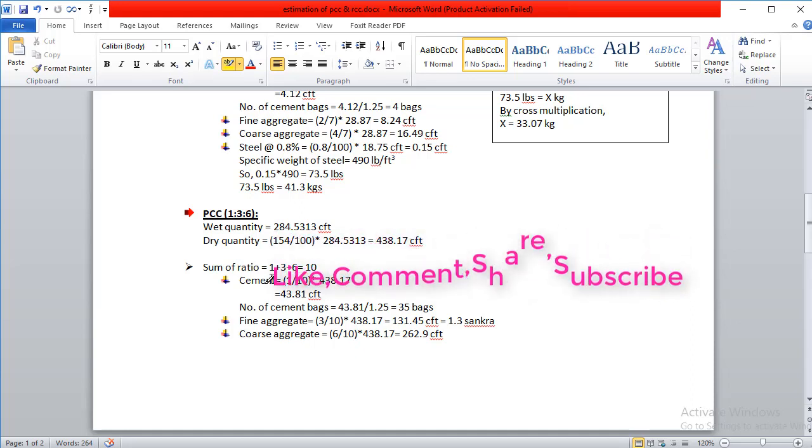Now the quantity of cement is 1 divided by 10 multiplied by 438.17, and I will get the quantity of cement, which is 43.81 CFT. Now to calculate the number of cement bags, we know the volume of one cement bag is 1.25, so just simply divide this quantity of cement by the volume of one cement bag, and you will get the number of cement bags, which is 35 cement bags that will be used in this particular PCC.